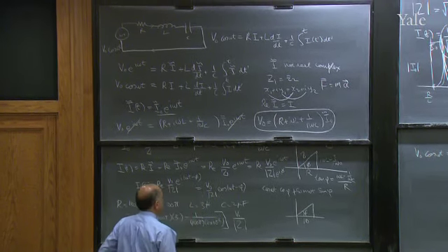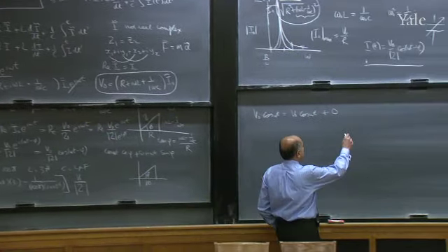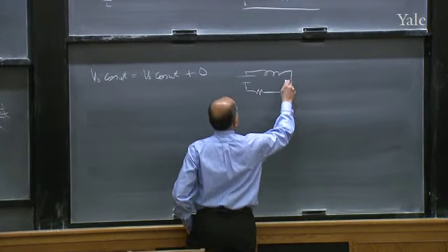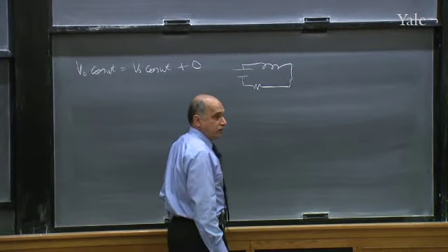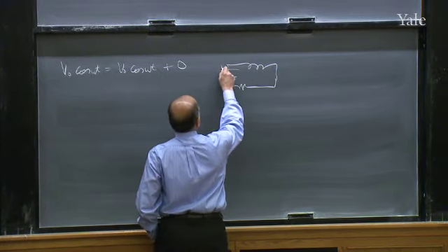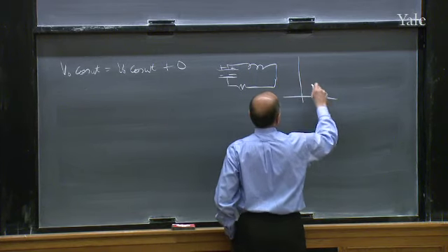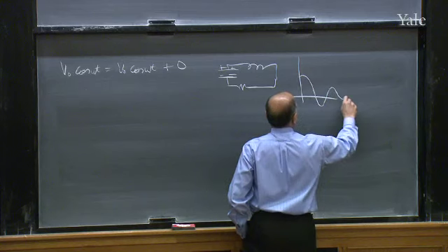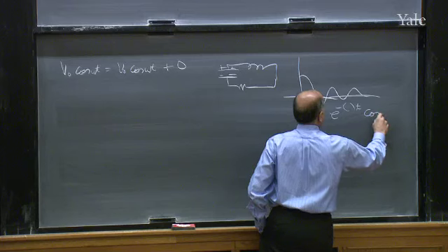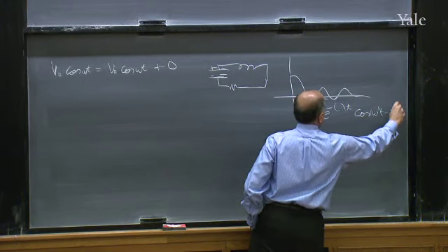And you might say there is no solution for 0 voltage, but I will have to remind you that we did solve the problem the other day of an LCR circuit connected to nothing. It had a current flowing for a while, but it won't do it if it's completely inert. But if you had put some charge on this guy to begin with, then you saw that the current and the charge, everything starts and oscillates exponentially, like e to the minus some number t times some cos omega prime t minus some other phase. Call it chi.